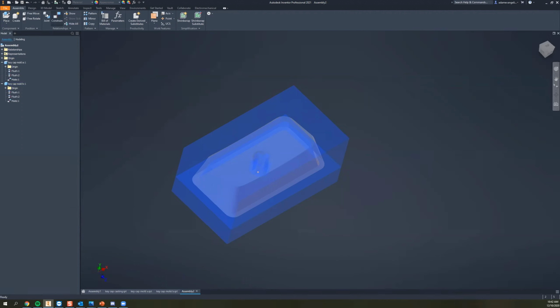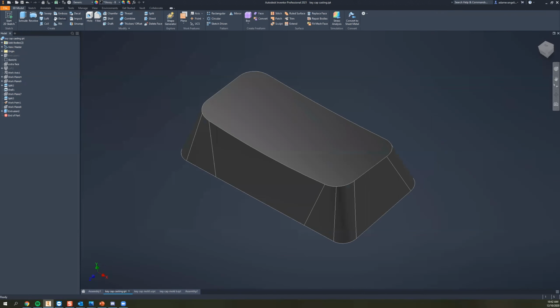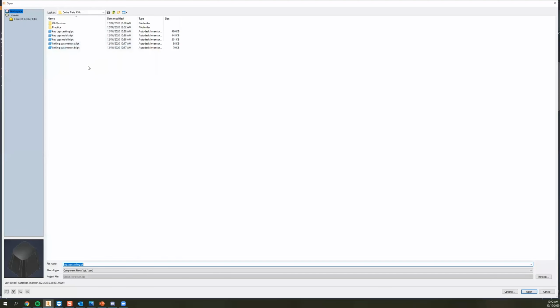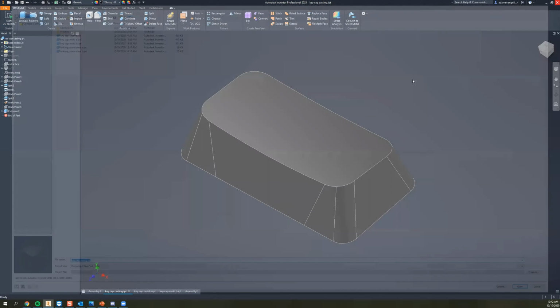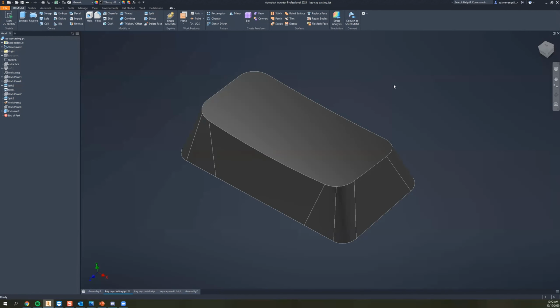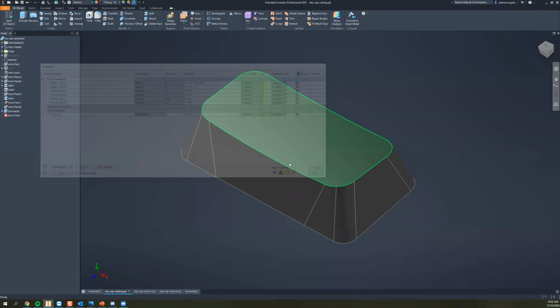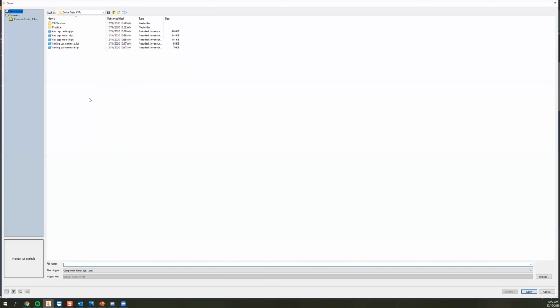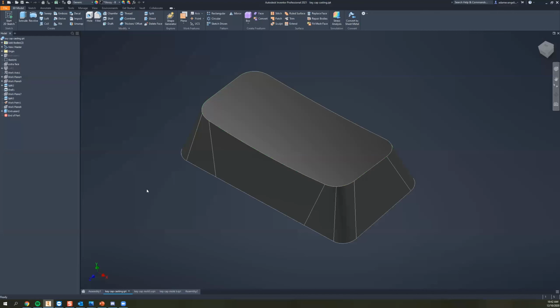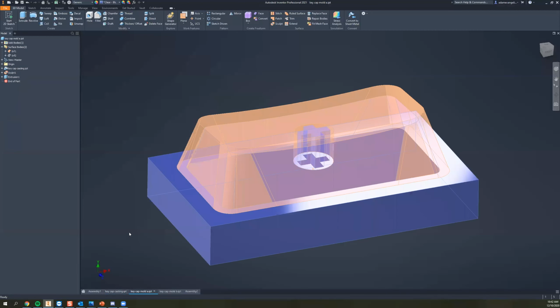And I think it gives a nice light to why these tools exist in the first place, right? Like the Derive command in particular, I feel like is a bit nondescript at this point. But again, being able to link information from one part to another part is an extreme utility in itself. Linking parameters is great, but I think it's only scratching the surface. Derive does pretty much everything Link Parameters does, plus you get all this extra solid geometry, which allows us to inform some more interesting design processes like mold making, for example.